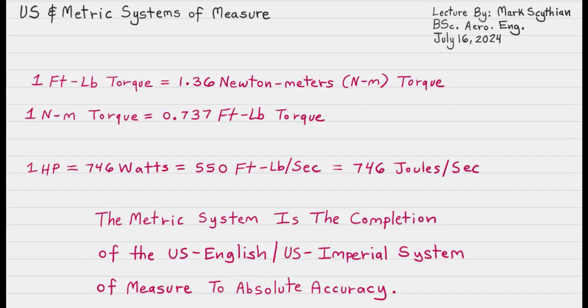So then we have the foot-pound torque. Everybody's familiar with the foot-pound torque with engines and the foot-pounds torque at a certain RPM, and of course the ratchets and the torque wrenches, etc. And so just like we had 0.737 foot-pounds per second to a joule or a Newton meter, we can use that standard or metric equivalency with the foot-pounds torque or torque moment. So 1 foot-pound torque is also equal to 1.36 Newton meters, because we know that there's 1.36 joules or Newton